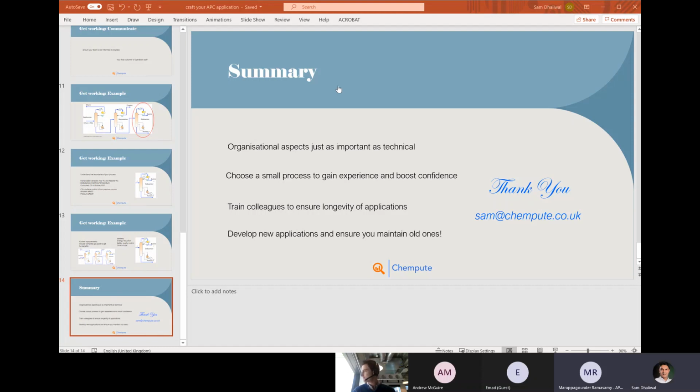Yeah, I think temperatures are quite commonly used as manipulated variables. I mean, it depends which one. But in this case, the temperature would be a part of the base layer scheme in any case, because in a distillation column, normally you will have one temperature that is controlled in the column, either the top temperature or the bottom temperature. In this case, I've taken the example as the TC in the top. And if we manipulate the TC, then you will end up getting the set point. Set point, okay, understood. Thank you.